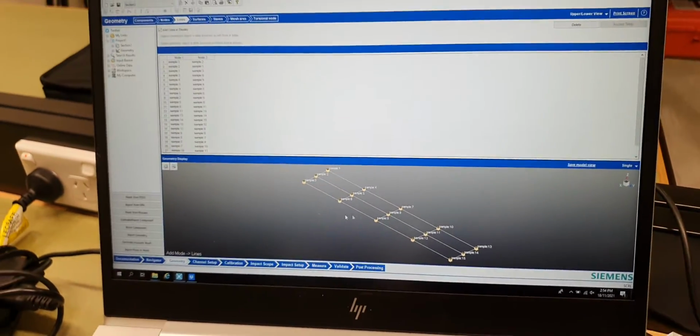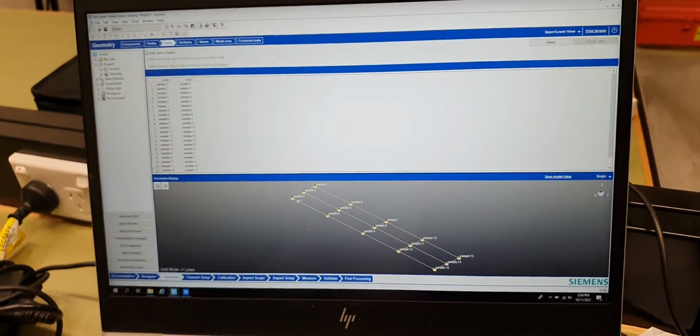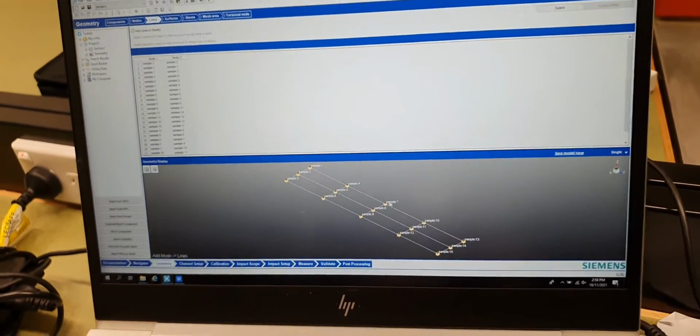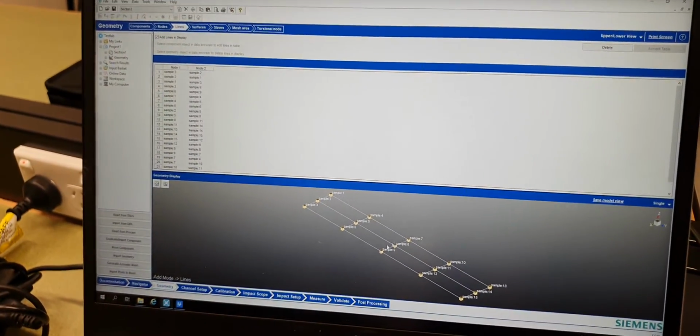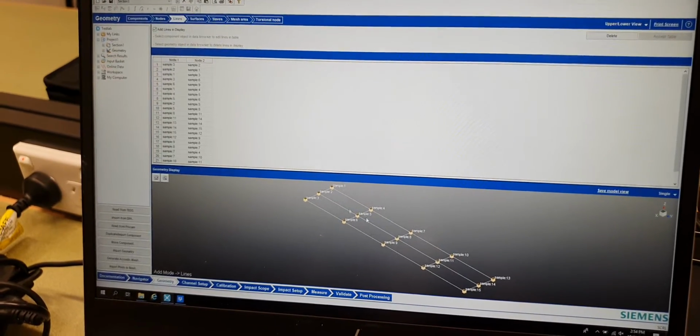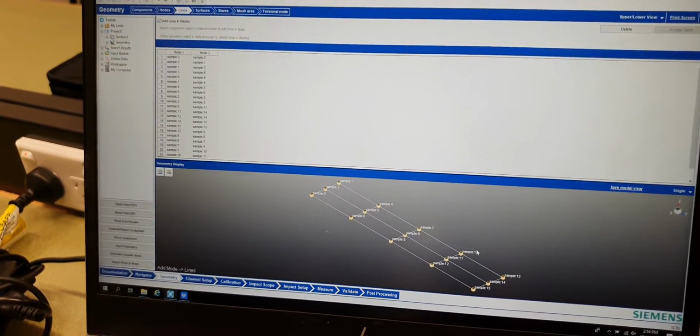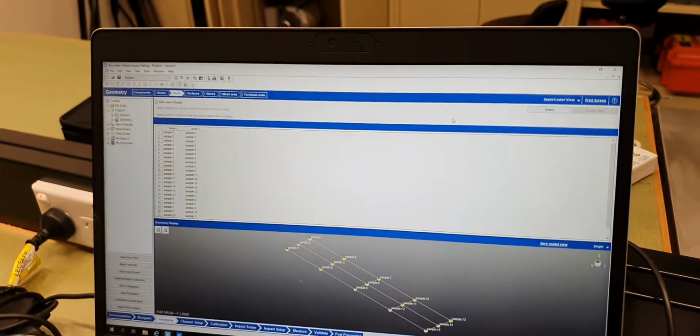So I fixed the geometry. We've got now a 3 by 5 grid of points here. We're going to be making the response measurement in the sample 8 location in the middle, and we're going to make excitation or impacts at all of the other 15 points in here.